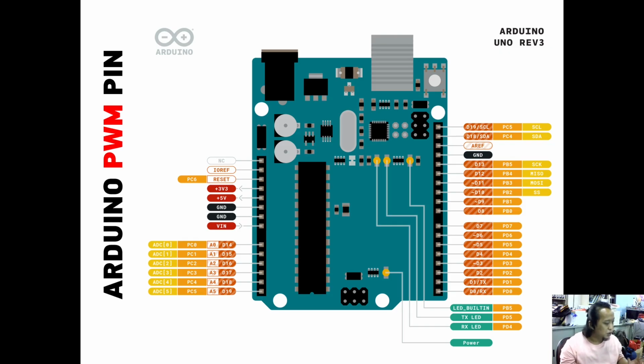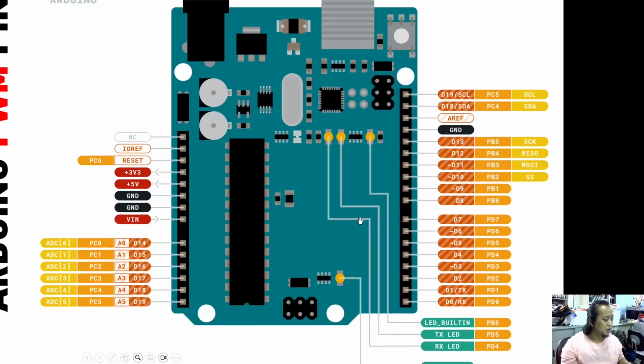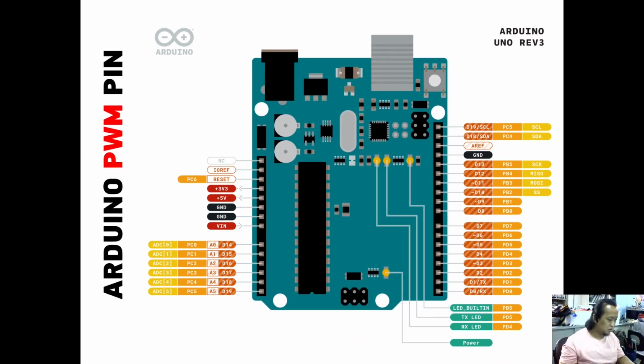And because we will use the Arduino, not all pins of the Arduino can be connected to a servo to control the servo motor. So it should be on some of these pins, the pins that have the infinity symbol like this one: pins 3, 5, 6, 9, 10, 11. Okay, that's a little bit of introduction about the servo motor. Thank you so much.